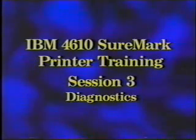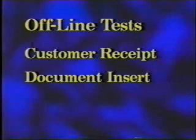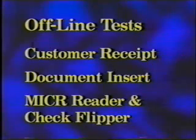In this session, you will learn the diagnostic procedures available for the 4610 printer. There are offline tests and online tests. The 4610 printer has 3 offline tests. They are the customer receipt test, the document insert test, and the MICR reader and check flipper test.